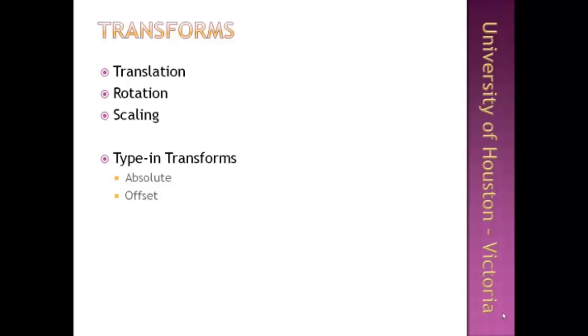Same applies for your rotation. If you drag one of the rotation arcs back and forth or up and down, it would rotate your object along one axis. If you drag 2 at the same time, it rotates it around a plane, and completely free rotation is when you apply it on the 3 rotation arcs at the same time. For the scaling operation, you can also scale either along one axis, along 2 axes, or along all the 3 axes, which will be a uniform scaling.